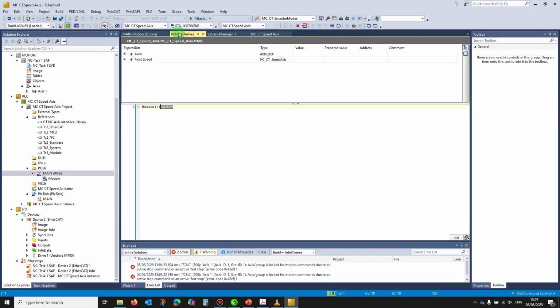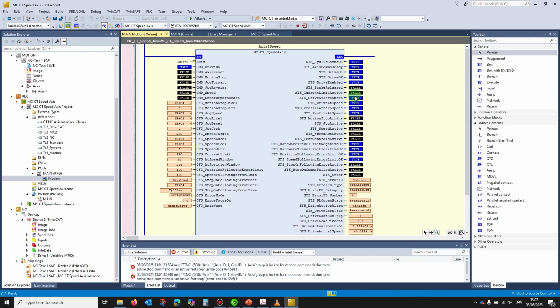So let's come back to the program. We've touched on these. We've got two values to be able to tell whether the comms are working. So SDO cyclic comms OK is basically telling us whether our SDO reads are up and working, so that we can read values like the trip values from the drive. This one tells us whether our EtherCAT comms overall is up and working.